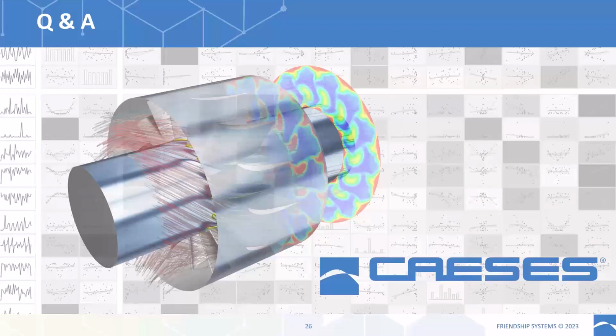And this is basically what is done by the airfoil blade, which takes a 2D cross-section of the blade as an input, so a 2D airfoil section, which is parametrized. It wasn't really discussed in a lot of detail, but you have different methods that you can use to transform your 2D definition into 3D. The easiest one is to simply use a cylinder transformation, which basically transforms it onto a cylinder with a given radius.